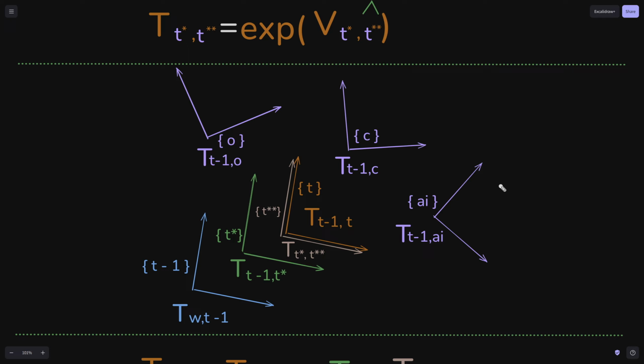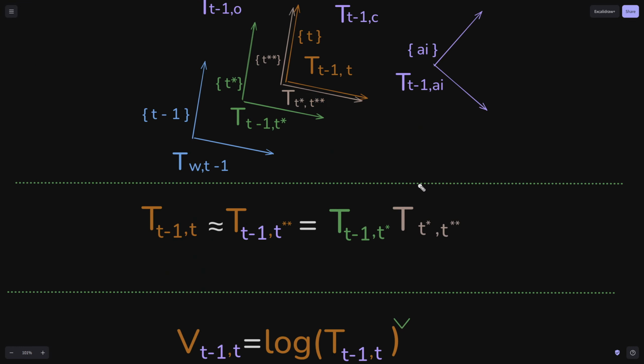This is done in robotics all the time. You have EKF and other algorithms where you all the time say, okay, I linearize here, I iterate, and by iterating it works, and graph SLAM works the same way. So this is no surprise here, okay?